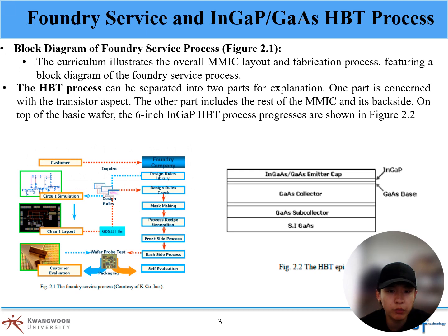The curriculum illustrates the overall MMIC layout and fabrication process, featuring a block diagram of the foundry service process. The HBT process can be separated into two parts for explanation. One part is concerned with the transistor aspect. The other part includes the rest of the MMIC and its backside.